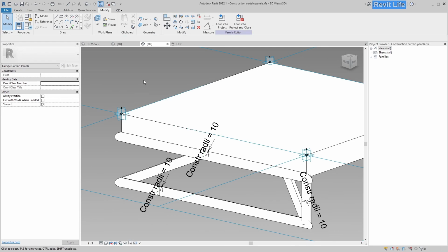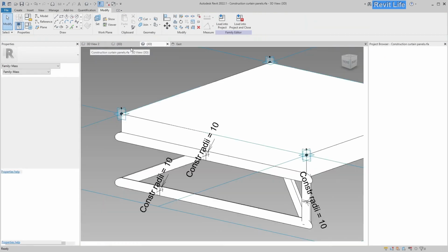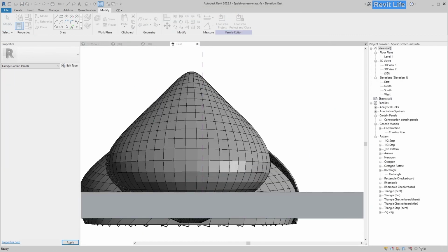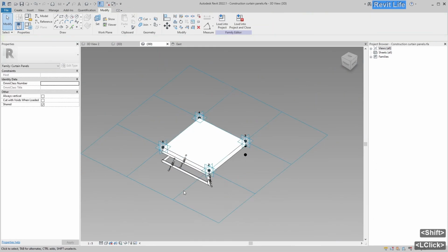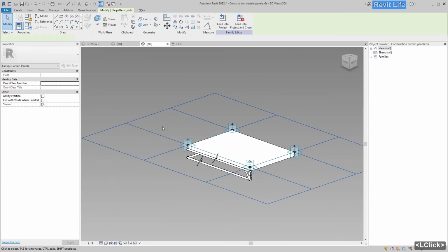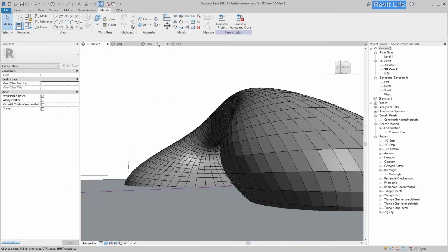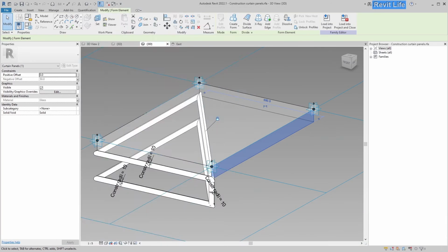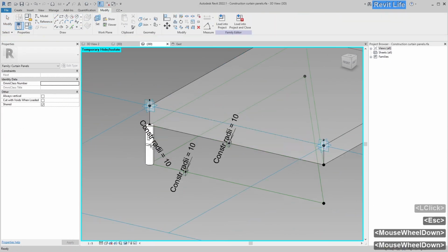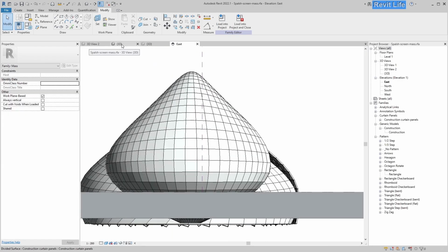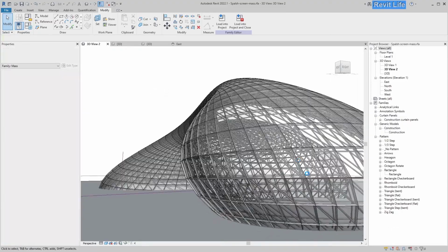And this is where the real fun begins, because I don't know why, but in the beginning I couldn't get the pipes populated onto the divided surface. So what I did, I made reference lines that are leading lines for those pipes, and then I made profiles for those pipes that are circles. And when I select those 2 reference lines, the circles and the leading lines for the pipes, and press create form, it creates a pipe. And that is exactly what I need. The problem was that I couldn't get the pipe that is perpendicular to the surface.